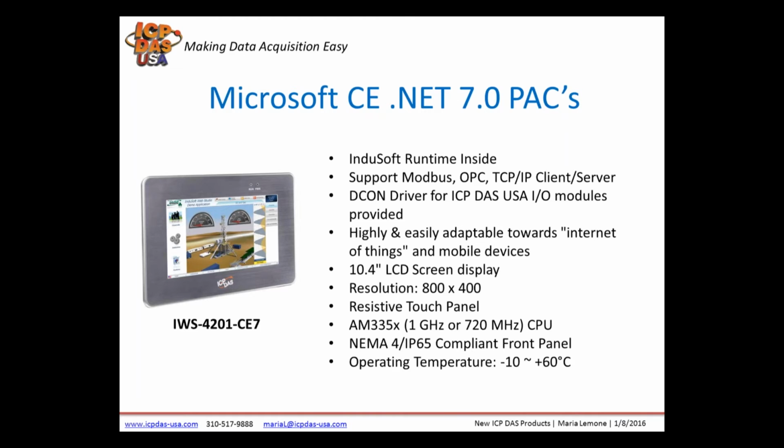The front panel is NEMA 4 IP65 rated, so this device can withstand being sprayed with water, extreme dust, and humidity. The fanless design offers quiet operation, and its casing and components can run under a wide operating temperature of -10 degrees Celsius to 60 degrees Celsius.